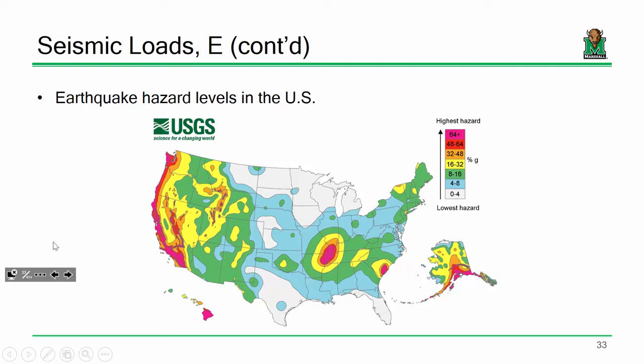It's more of a matter of our risk of damage and our risk of danger if an earthquake were to occur. I mean, if you look here, this seismic hazard level, this is Western Kentucky, right? And this is just as large of a seismic hazard level as out in LA, okay? So if you're designing a building out in that region, you've got to design it just the same as you would out in LA. A lot of people don't realize that, but it's all about risk, okay? If that region were to go because it lies along a fault line, it would be bad, okay? So we have to address that accordingly. Does that sound good? All right.